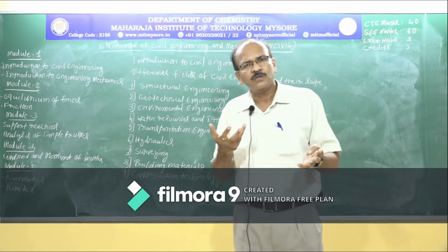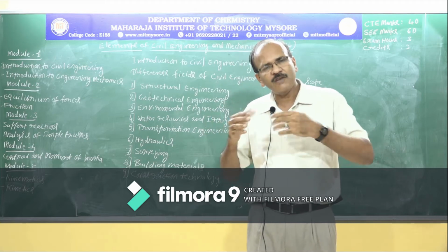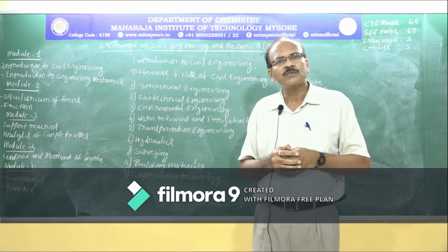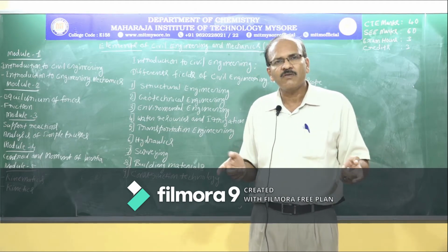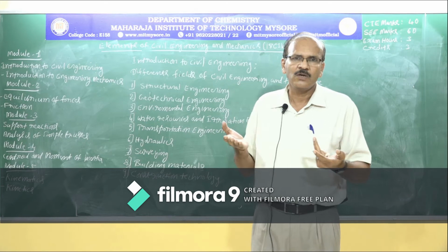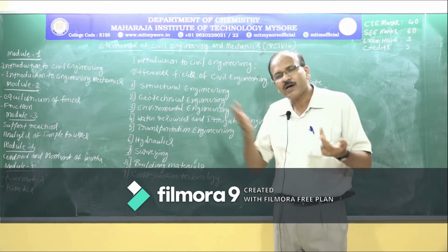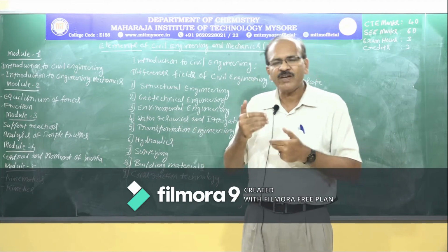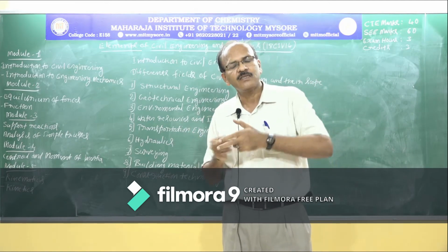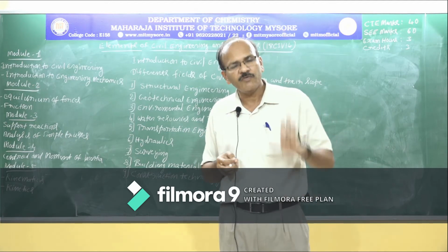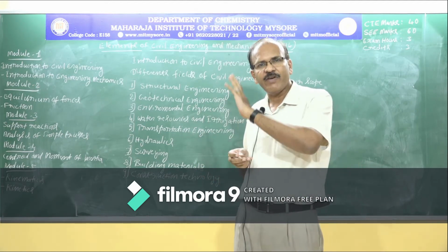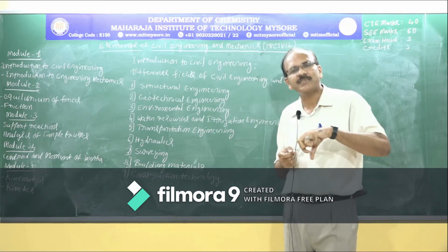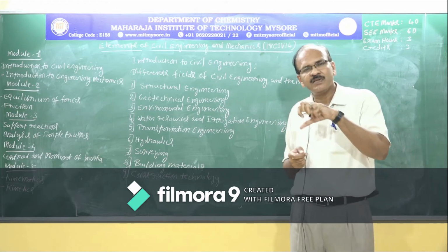What are the dead loads? Dead loads are the permanent loads, like the self weight of the structural components or bridge elements and the road surfaces. What are the live loads? Vehicle loads. So vehicle loads are the live loads coming on a bridge. Okay, we also take the impact effect into consideration, because the loads will be moving and we apply brakes and accelerate a vehicle.